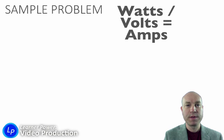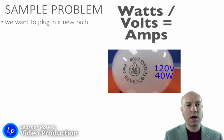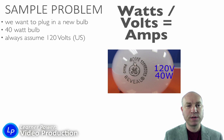Let's try applying that formula in some sample scenarios. Always remember that watts divided by volts equals amps. Okay, first scenario, we want to plug in that bulb right there. This is a typical kind of bulb that you might use in your house. We don't use these for professional video production, but if you look closely, you can see this one says 40 watts. All right, so if we want to plug in a new bulb, and that bulb is a 40 watt bulb like this one, and we're always going to assume 120 volts, then our formula looks like this. 40 watts divided by 120 volts gives us an answer of 0.33333 repeating. I didn't put all the threes because they go to infinity.